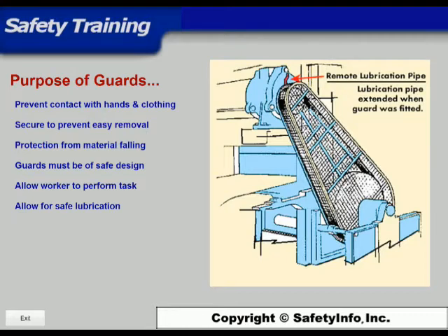Locating oil reservoirs and grease points outside the guards with a line leading to the lubrication point will reduce the need for the operator or maintenance worker to enter the hazardous area.